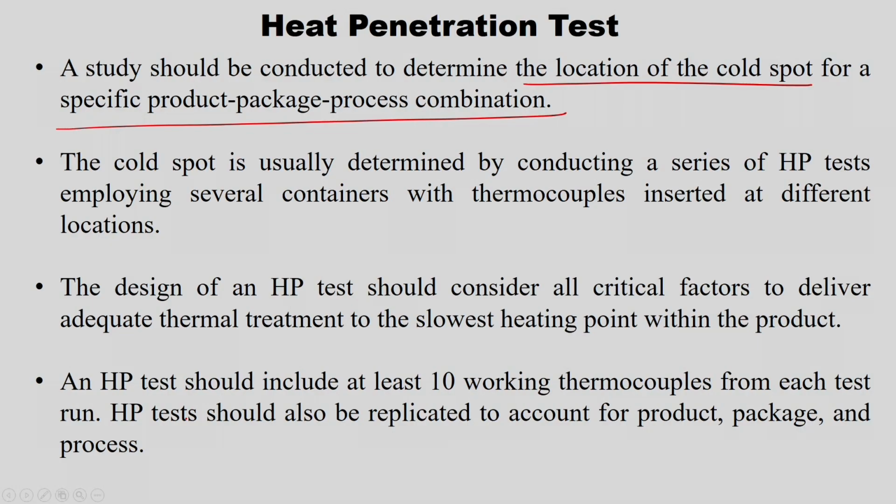So, if I know it is a cylindrical can and if I know the products are fully solid particles, then I can say the geometric center would be the cold spot. However, we need to insert the thermocouple and also ensure that it is the cold spot of the product package process combination.